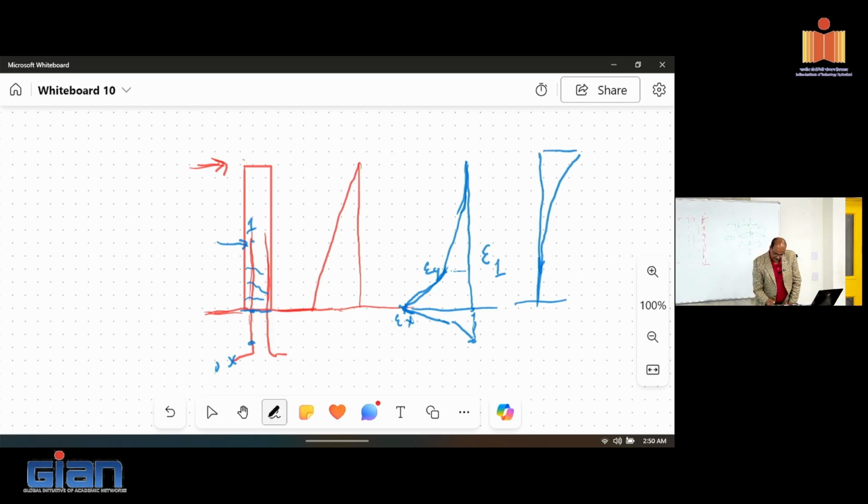This deflection is going to come from, basically, the deflection is tied to curvature. Curvature is tied to strain. So if I can plot the curvature, I'll do it here, which is going to have a similar shape as this. So your curvature is going to be like this all the way to here. So that's going to be your curvature as a function of height. So all of this curvature, if I integrate it, it will give me some displacement, which is this.